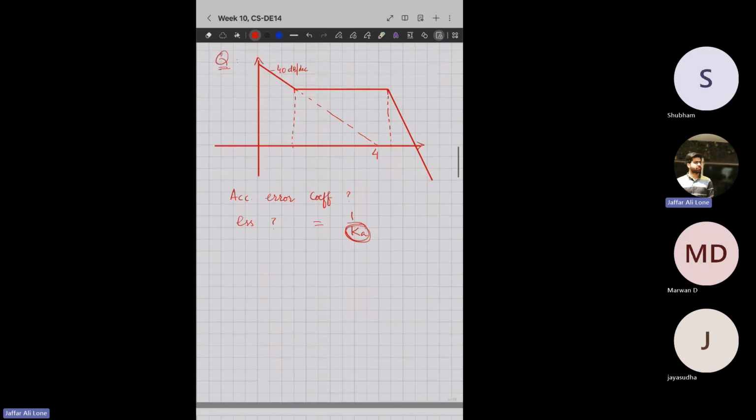So nothing is given. Whatever we have been doing, we were saying initial magnitude, but initial magnitude is not given; something else is given. Make use of this dashed line. Apply your brain and see what we can do with this dashed line. Here the slope is minus 40 dB per decade because I'm just extending this 40 dB per decade line. So first of all, you should know the system is